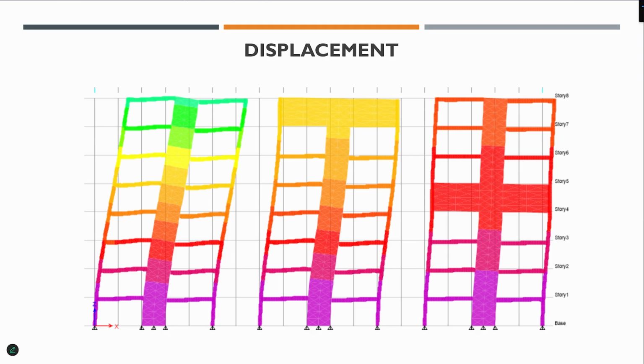Okay, why is the one in the middle more effective than the one at the top? Because in this case, only this much length is subjected to axial shortening and elongation. So for the same column size, the stiffness is EA over L, right? The L is the main parameter. So when you divide by the long length, the stiffness becomes smaller.